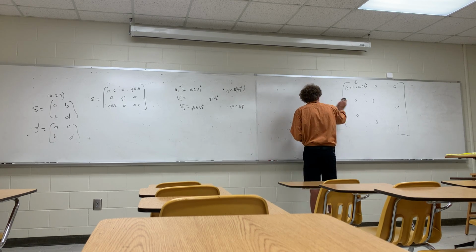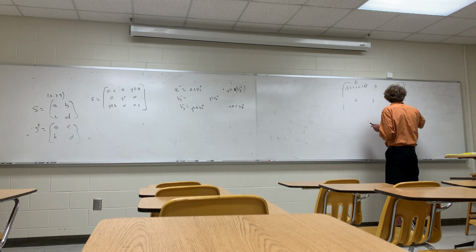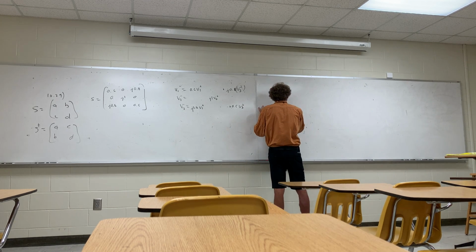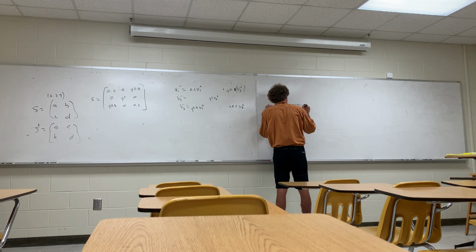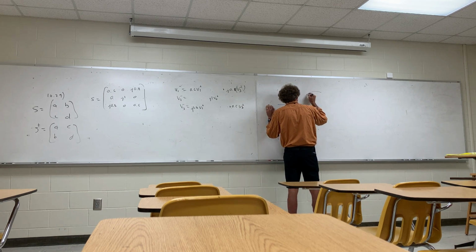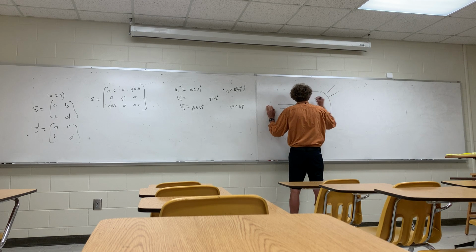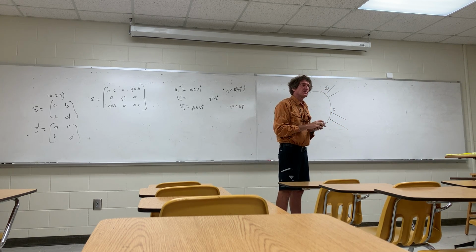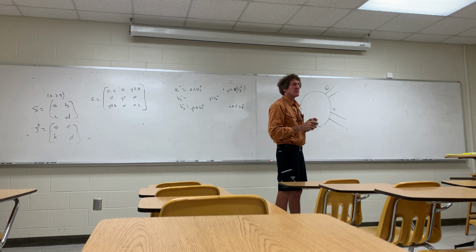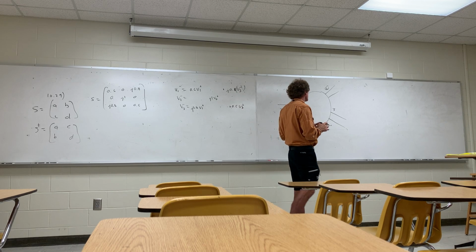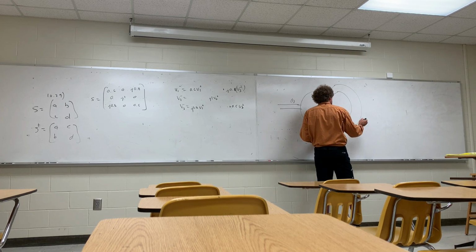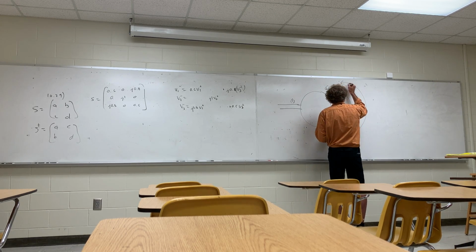This is a pretty big problem. So if I have this, I've got port 1 right here, and I'll do it this way. It's not a circulator, but I'll make it look like a circulator. This is port 1, port 2, and this is port 3. And he says something about port 2 and 3 being tied together by? Determine the return loss at port 1 if ports 2 and 3 are connected together by a matched T line of electrical length 45 degrees. All right. So he's saying that across this, there's 45 degrees of change.